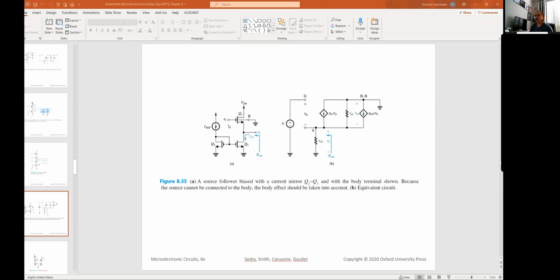Now, one thing that is in here that I want to call your attention to is the fact that when we have transistors stacked, like we have Q1 on top of Q3, and we've seen that before, but we're bringing it up here because it's simpler to manage and explain here than, let's say, in the context of the 4 transistor cascode that we just saw. When we think about transistors, we think that the source and what we call the body are tied together. Most of the time, that's the case. We can tie it together, but it may be that sometimes that's not possible.